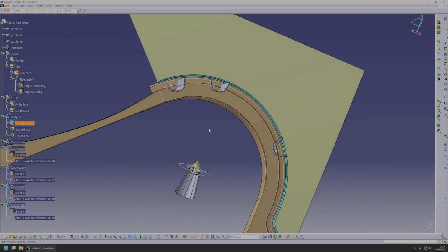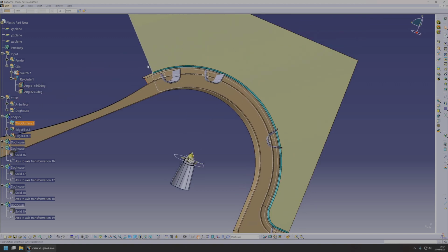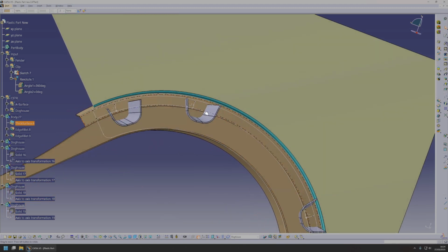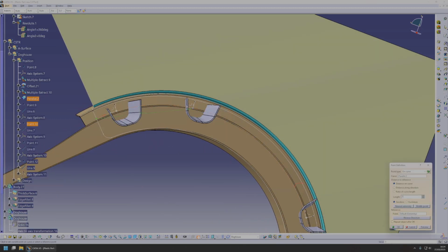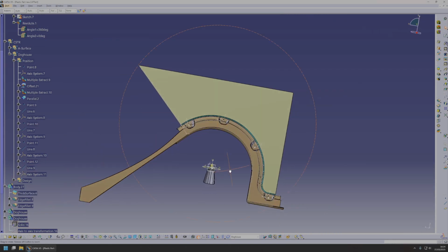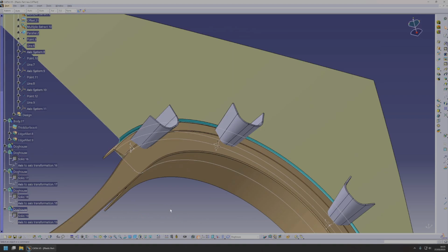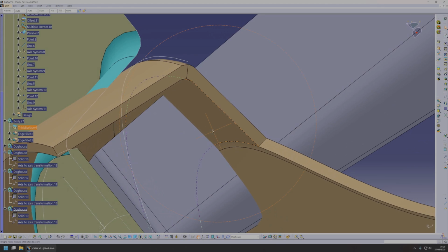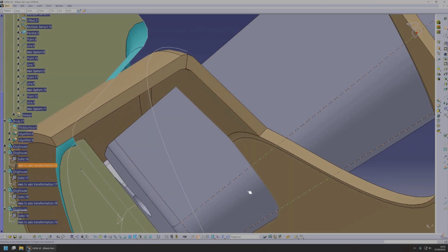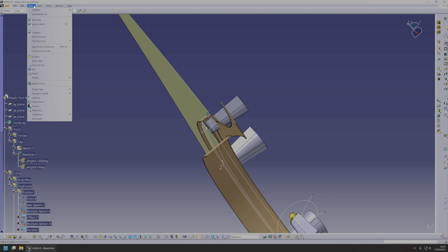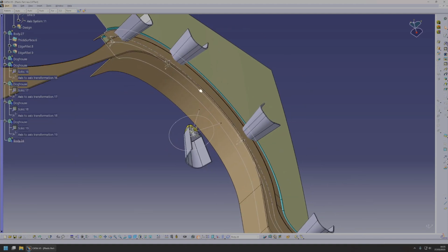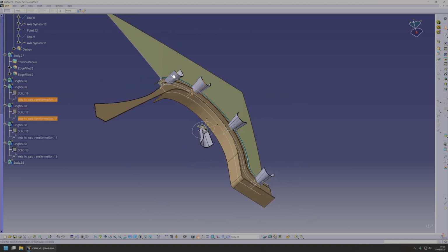Right, so you could do this manually for each of these doghouses, or you could do it automatically, which is how I'd like to do it. Just a second, this kept annoying me. Yeah, now it's more evenly spaced. So first things first, we need to stop this thickness at a certain point. We want to stop this somewhere here. So in order to do that, we create another body, and we join all these features together in a single body.